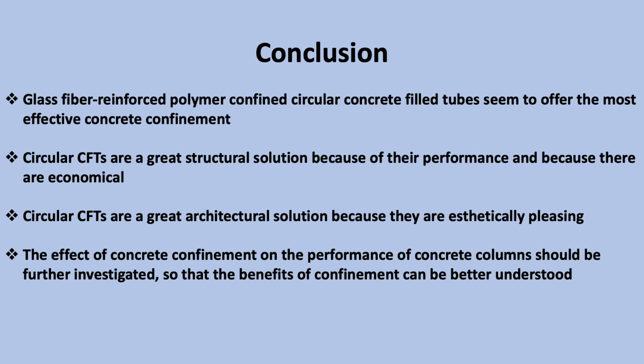We can conclude that glass fiber reinforced polymer confined circular concrete filled tubes seem to offer the most effective concrete confinement. And we can also conclude that circular CFTs are a great structural and architectural solution because of both their performance and the fact that circular members are aesthetically pleasing.